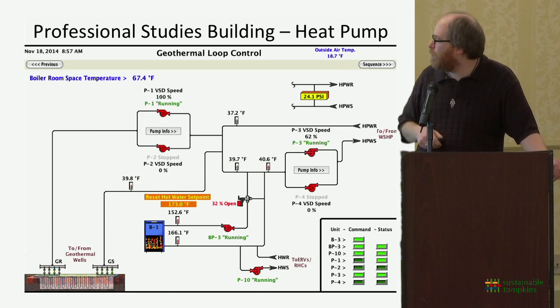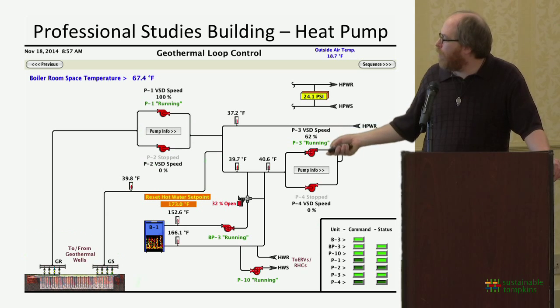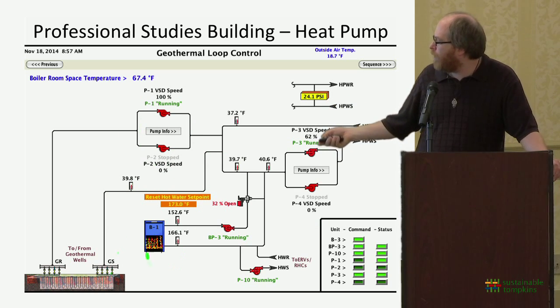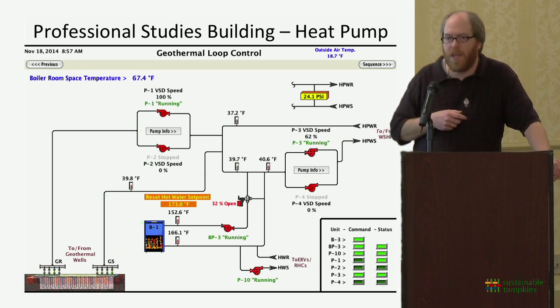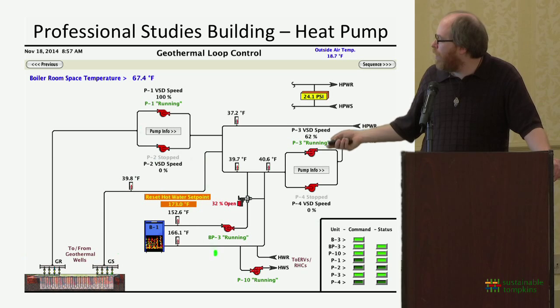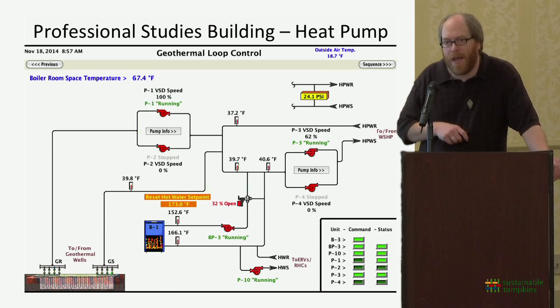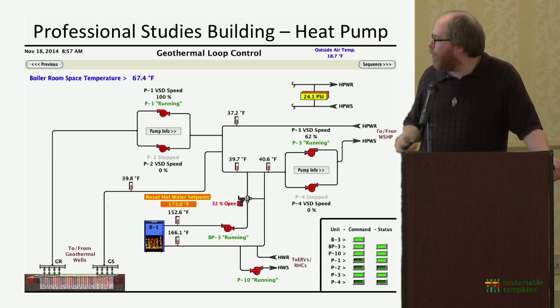So Cortland's system is a hybrid system. It's not yet done with biomass. We have our ground wells here that feed into this part of our control loop, but we also have a boiler system here that can augment the heat from our ground source heat pumps. Right now, this is driven off of natural gas because the rest of the campus is, but our climate action plan envisions changing all of these out eventually to biomass boilers.